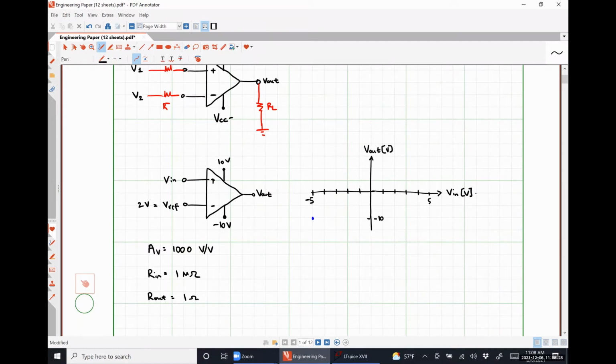Okay, is -4,000 more negative than -10? Yes. So what is our real output of our system when Vn is equal to -2 volts? -10. So we're still in negative saturation, right? So here's -2. Just for the sake of argument, we can connect these 2 points because there's no reason anything should have changed anywhere between -5 and -2 volts, right?